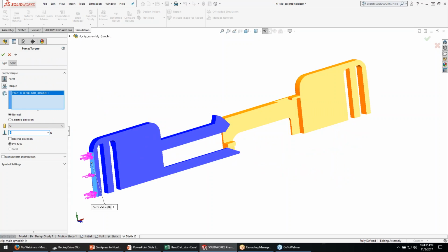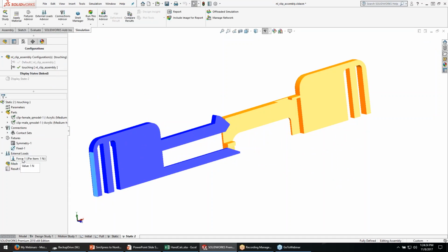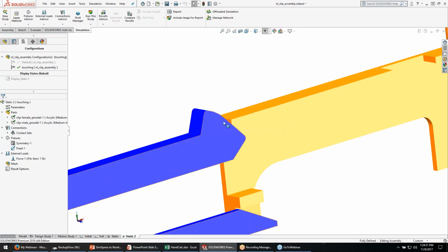And it's tempting. Maybe I'll start off with 1 Newton, because if I do 1 Newton, that should not be enough force to cause this thing to slide. And as I increase the load, I'll experiment with increasing this load and see the kind of result behavior I get. Okay, but starting with 1 Newton, I should just see this thing slide a little bit and then bend downward.